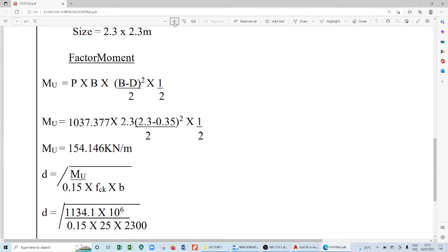So meaning this, to get the actual depth, I say the overall depth. So we have the effective depth plus the bar size, bar diameter plus the concrete cover. So meaning that overall depth I'm going to calculate, it will be my 6.78 plus the bar size. I'm assuming I'm using 16 divided by 2 plus 50.